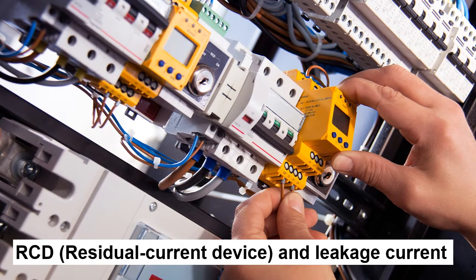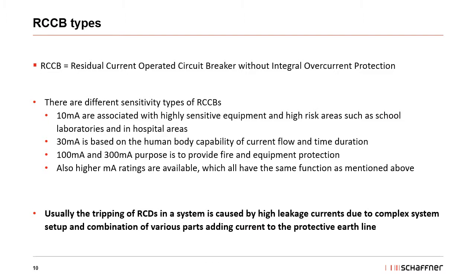Now we are already coming to the RCD or residual current device and leakage current. RCD is clear what it is. So it's a residual current device which measures the residual current on the earth and disconnects the system in a failure. So RCCB means residual current operated circuit breaker without integral overcurrent protection.